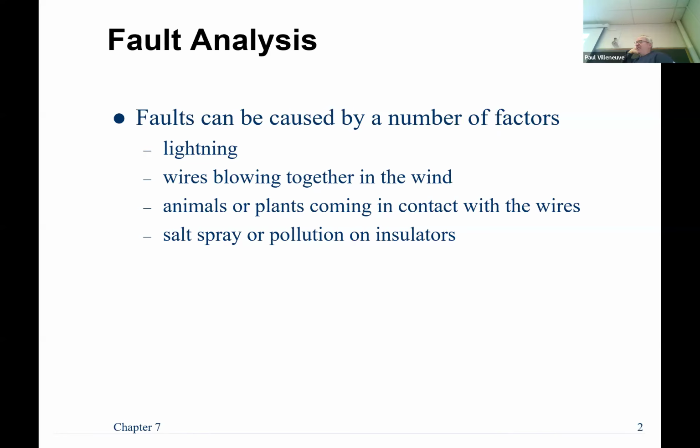I saw somebody in Texas in the past 6 months who went to work on a medium voltage system. They expected it to be de-energized, and instead of confirming that it was de-energized, they actually started working on it and they got severely burned because, unfortunately, it was energized. And so there are things in place now that can provide some protection for yourself, but it's fairly limited. So human error is another very common one, but hopefully that's getting less and less common with operating procedures and whatnot.